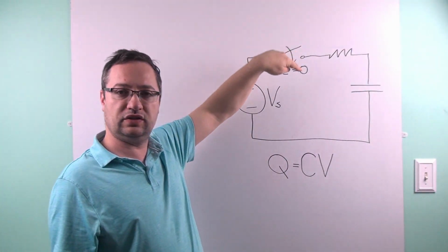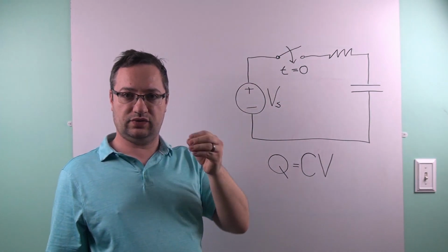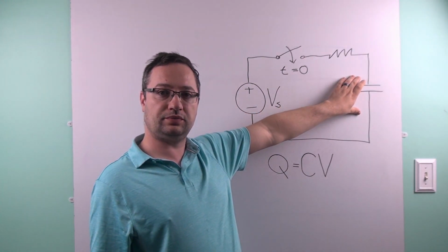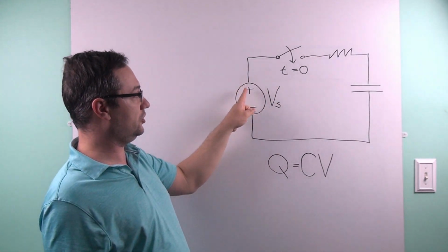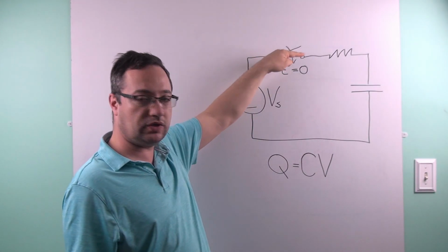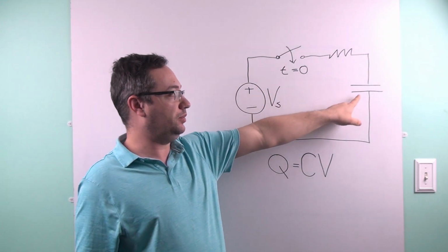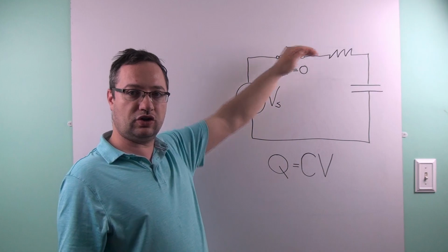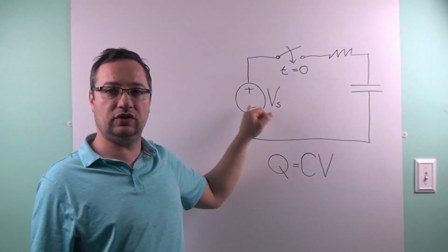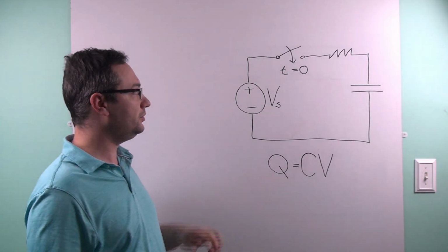And that's at t0 when you throw the switch. When you throw the switch, very initially, what you get is 0 volts here. A current starts to flow from the source, because it's 0 volts here, this way through the switch and then through the resistor. And initially, because the capacitor is not charged, the current flow here is basically just dictated by the resistance and the source voltage.